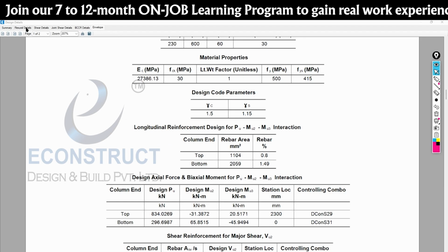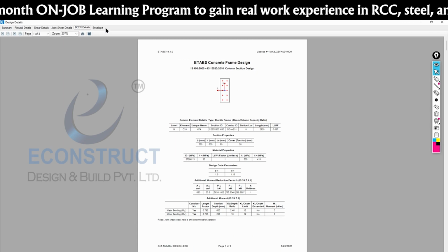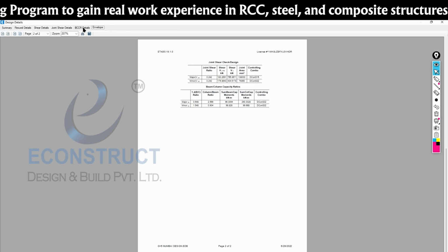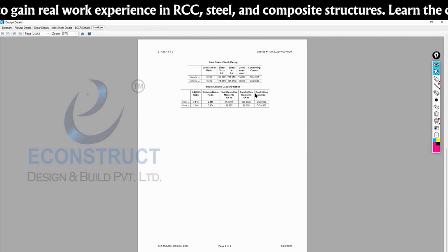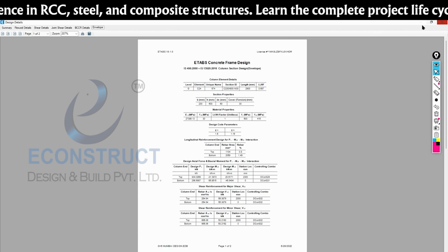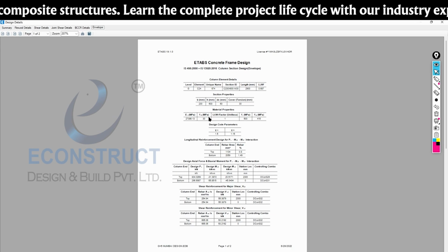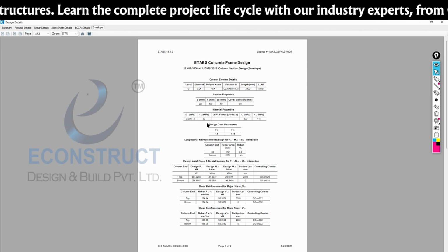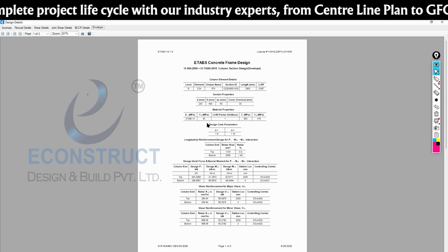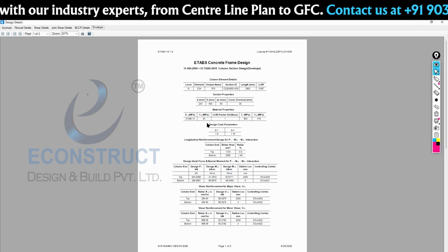Today we have completed flexure, shear, joint shear, BC shear, and envelope also. So envelope means from all the sheets, what are the things that are important will be given in your envelope. Maximum value it will take for design. Maximum value of all the moments for design it will take. Maximum value, how will it depend? It depends upon the section only. There is no limit for maximum.